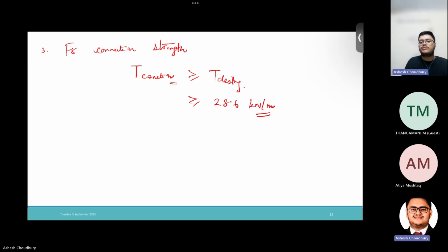If we do not allow proper drainage of water, a huge amount of lateral thrust due to water will be acting on the wall. To prevent that, we use some drainage. These are the face, right? So we provide some drainage layer here, maybe in front, in the form of cohesionless sand or say gravel. We provide some drainage layer here.